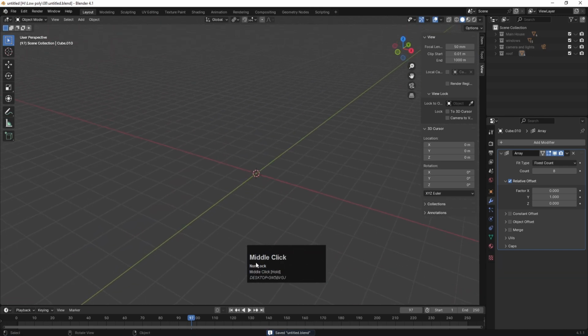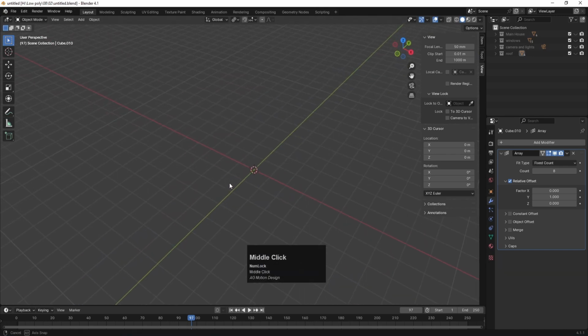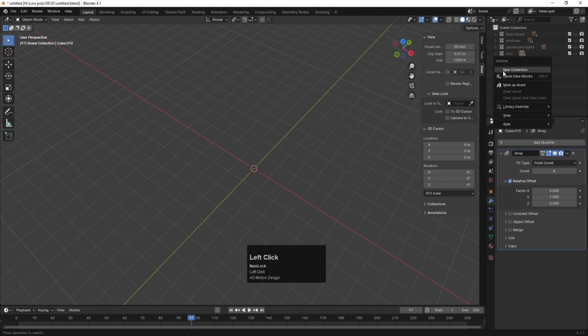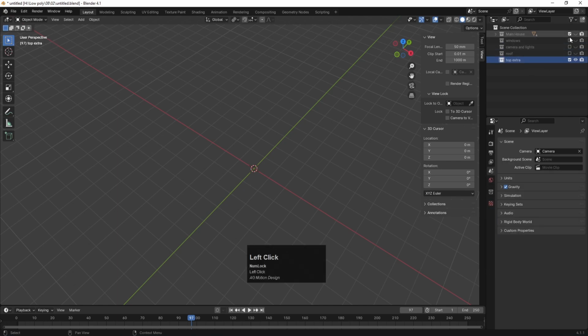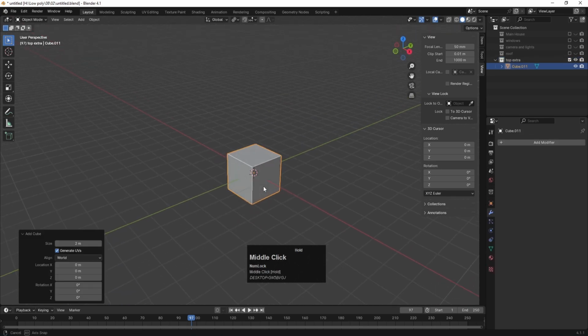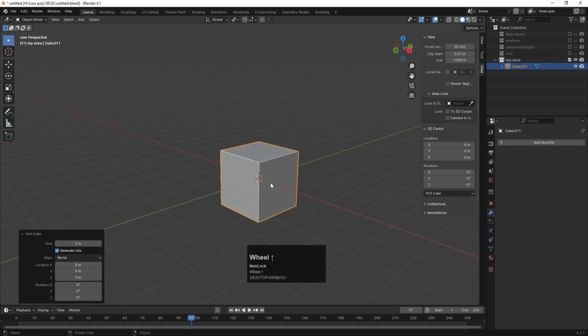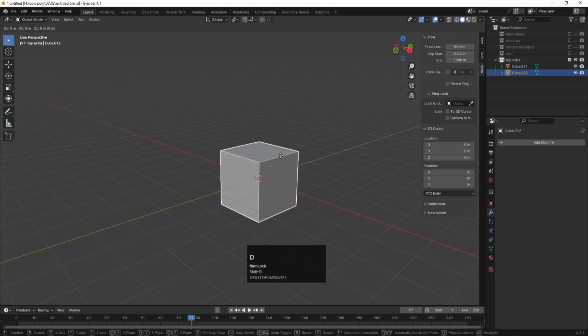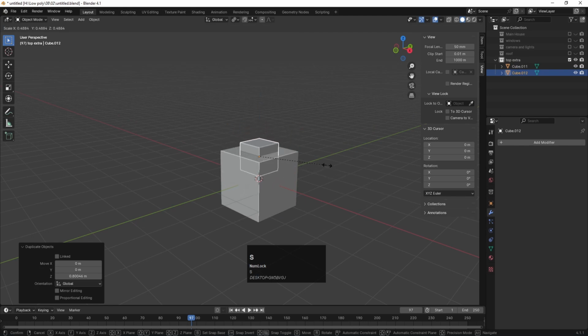extra things over here. Okay, so to create some extra models, let's right click new and double click and let's call it top extras like this, and let's uncheck all of this. So like that, whatever we are going to create, it's going to come over here. So to do that, simply press Shift A, mesh and choose cube like this, and after that Shift A, or you can simply select this, Shift D, Z and try to bring this, press S and let's scale it like this, G Z and try to bring this upward.